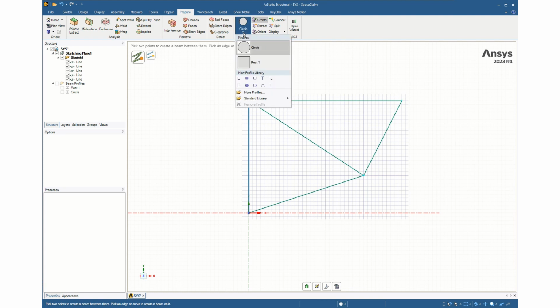I need to have another solid steel circular member that's got a different radius, so I'll click on that again. And this is where I could go change those names if I needed to help me understand the part that was being made. Then I have a hollow circular tube, so I'll click the drop down, click on the tube and hit create, and I've created a circular tube.